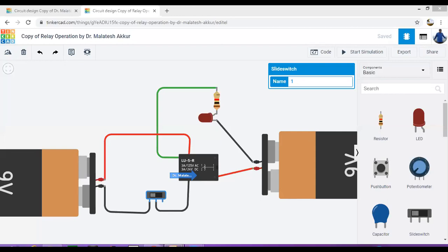As I said, this has the transmitter and the receiver. This is the distance, and you can see the equation. The distance is measured as time multiplied by the speed of sound in air. The ultrasonic waves travel at 340 meter per second, or more accurately 343 meter per second, divided by 2, because the measured time covers the wave traveling from the sensor to the object and from the object back to the receiver. Once we divide by 2, the distance is exactly from the sensor to the object.